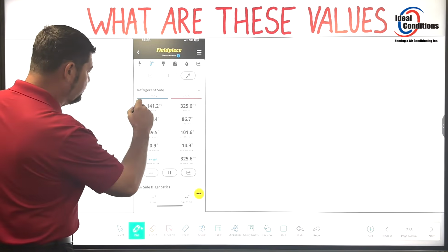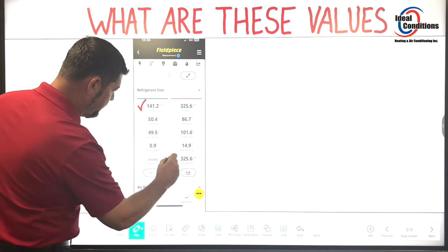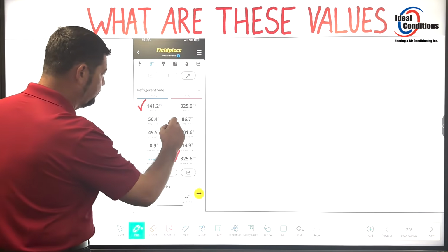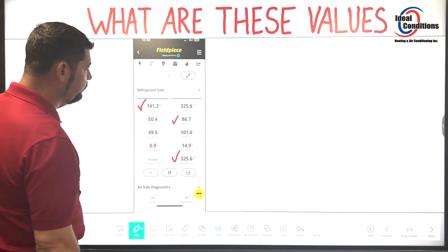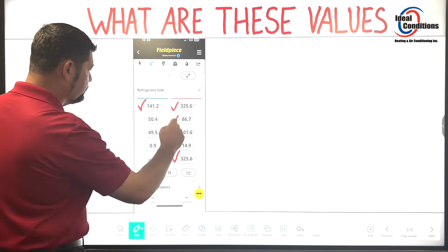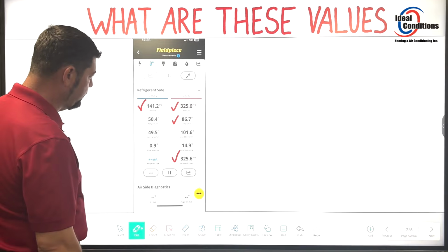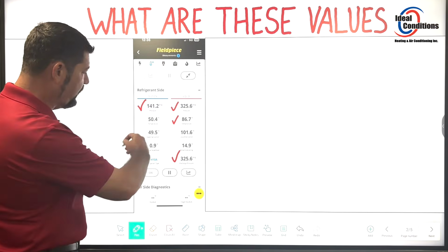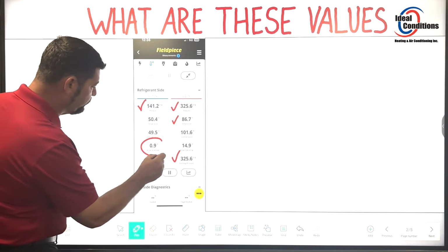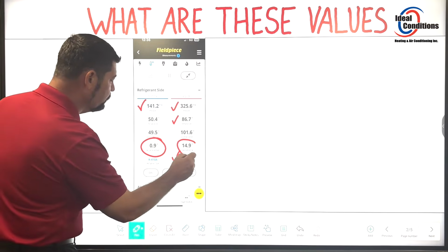Well, I'm going to say that, you know what, that looks pretty good here. If I just went off these pressures alone, man, that's pretty darn good. And it's 87 degrees outside. Yeah, that all lines up so far. Yep. That liquid pressure, that's good. Uh-huh. So where's my problem? It's 410A. Where's my problem? What do these values mean? Well, what I'm looking for is my superheat. What else am I looking for? My subcool.